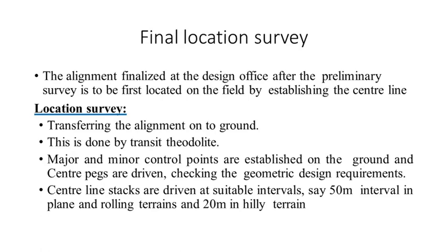Checking the geometric design requirement. Center line stakes are driven at suitable intervals, say 50-meter interval in plain and rolling terrain, 20-meter in hilly terrain. Okay. So the purpose of final location survey is to lay out a final center line.